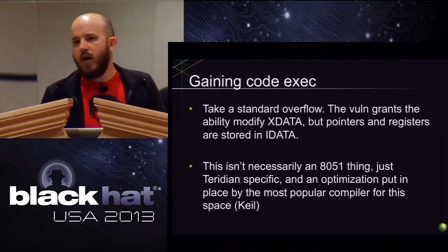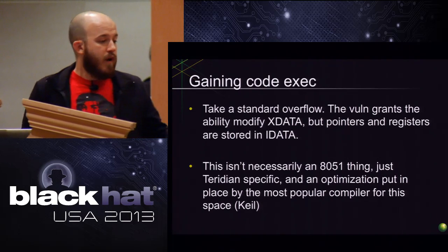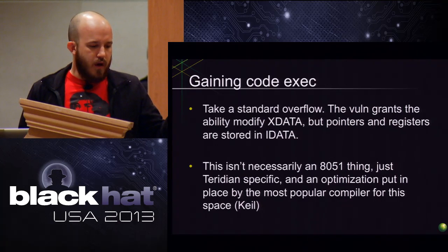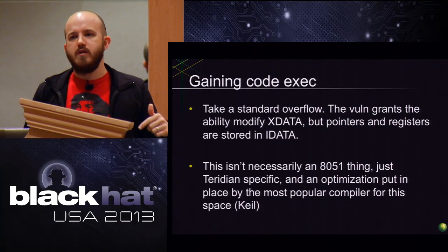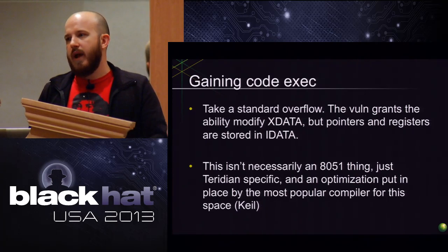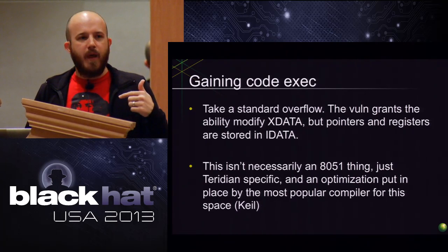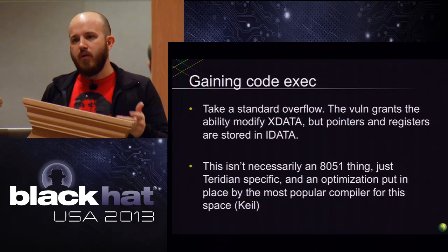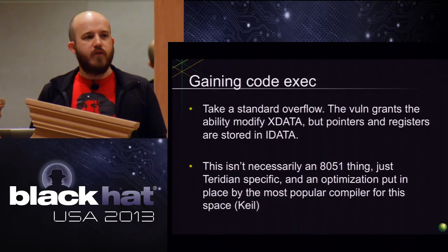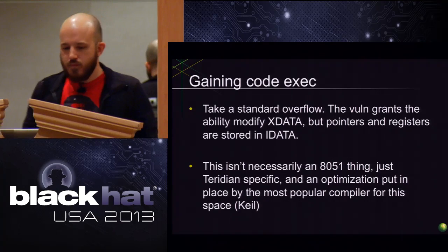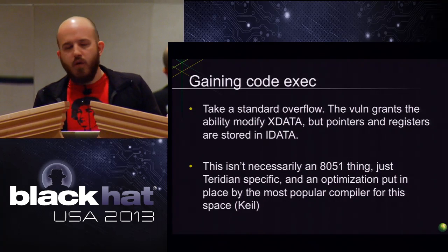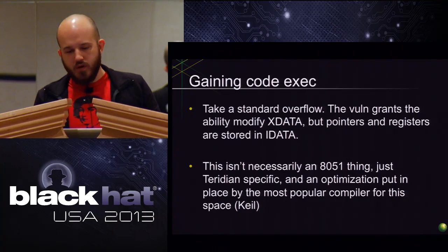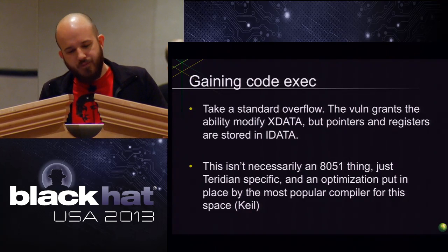There are other implementations. I think Travis's talk that we plugged earlier speaks of another 8051 implementation where this is doable because the stack is in a location that is bigger in comparison, and so the compilers for that one don't do this sort of trick where it sticks the stack over here and sticks the data over here. So in those cases, standard buffer overflows would work just fine, but they won't in ours, unfortunately.